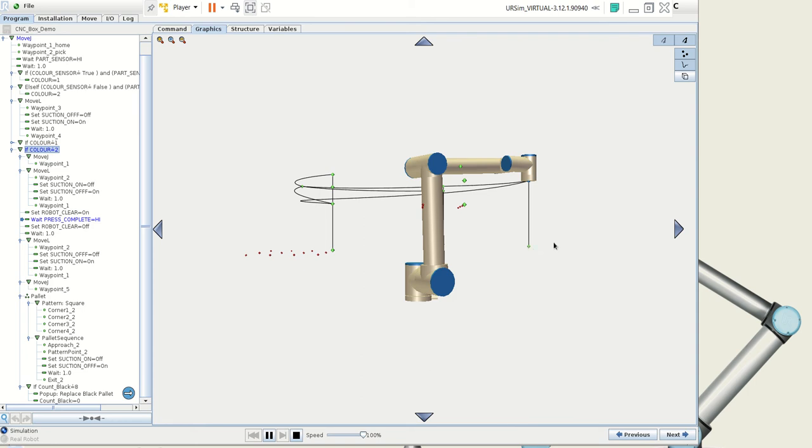What we're expecting to happen, if you can imagine there's another machine over here that's separately controlled, maybe by a PLC or something like that, is that when the part's in there, it's just going to come down and drill a hole in it or something like that. So there's a separate bit of I/O, a separate bit of machinery over here that's doing that job for us. But how do we interface a wee bit of communication between that to let the robot know something's done and it's ready to be picked up again, so that we don't get the two machines colliding?